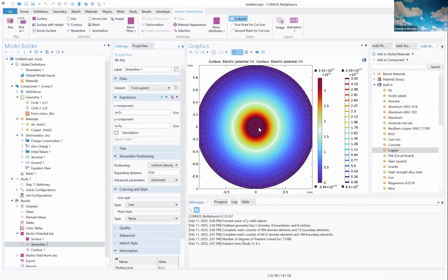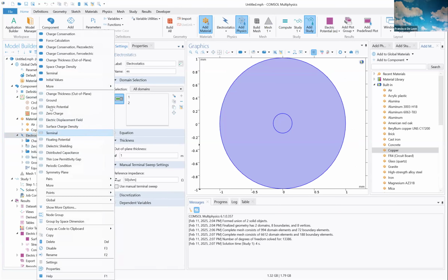I asked the same question, Professor. Professor says that it is just because of the meshing. Okay, so it's not considerable. And we know that the electric field inside the conductor is 0. I have tried with a different boundary condition, like this terminal. I tried and selected it as a domain, and in this, they were not there. Oh. You can try this terminal. That's why I mentioned these options here. You also have this terminal boundary condition, and it will take this whole conductor as a domain, right?